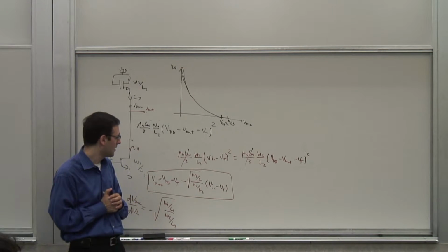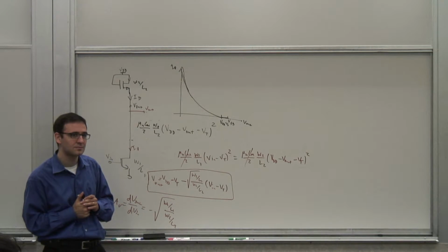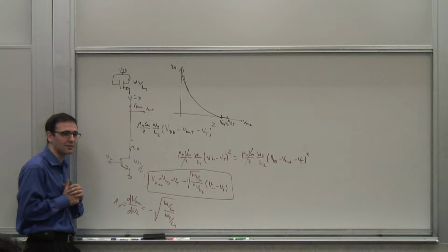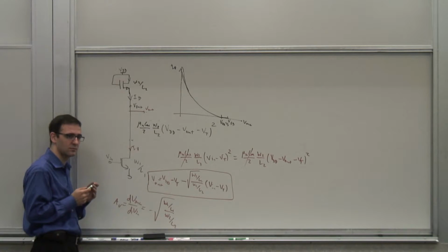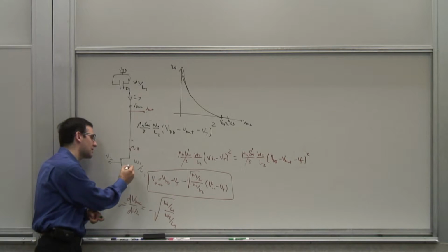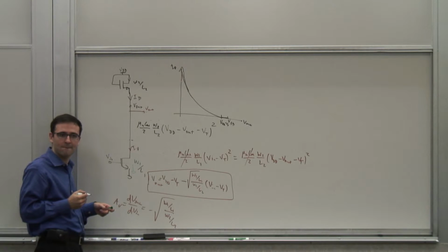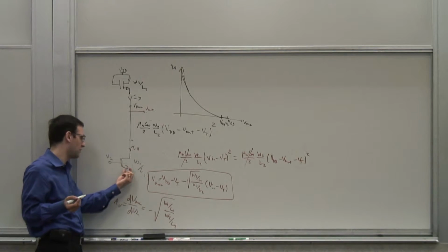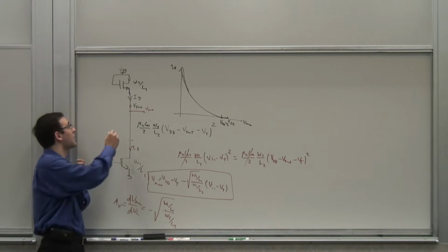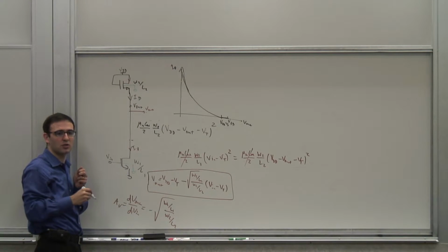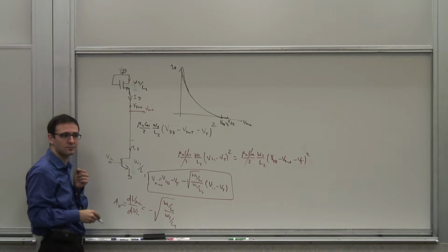VT, right? What is the problem? Assuming that the threshold voltages are the same. Yes, that's exactly what I'm assuming. And why is that assumption not valid? Right, because this transistor doesn't have any body effect, because both the gate and source are at constant potential. So the VDS from a small signal perspective does not change. However, this one has its bulk constant, but its source is moving, which is the out.